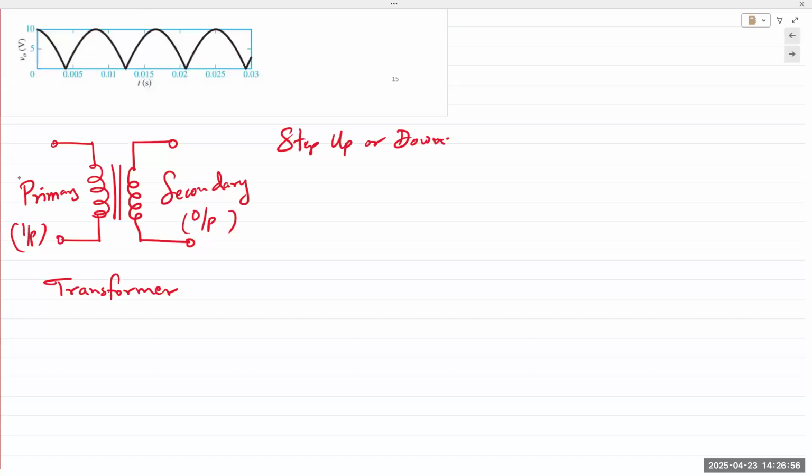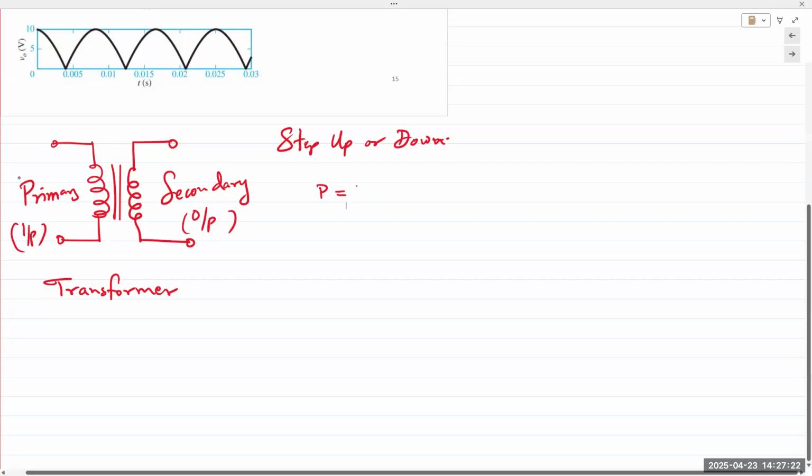Long distance transmission lines, long distance power, is always transmitted with AC, because AC power generation is very easy, or easier than DC. And then here's one of the reasons why we need to increase the voltage when you transmit electrical power over long distances. Electrical power is the product of the voltage and the current. Standard equation, V times I.